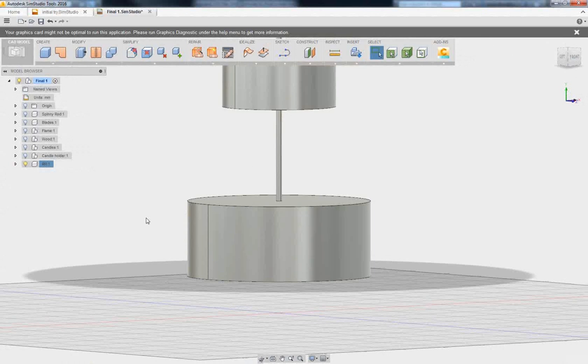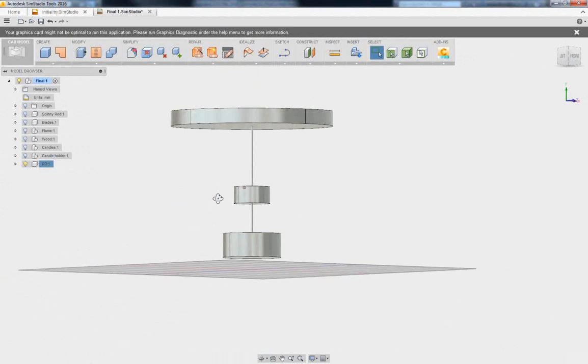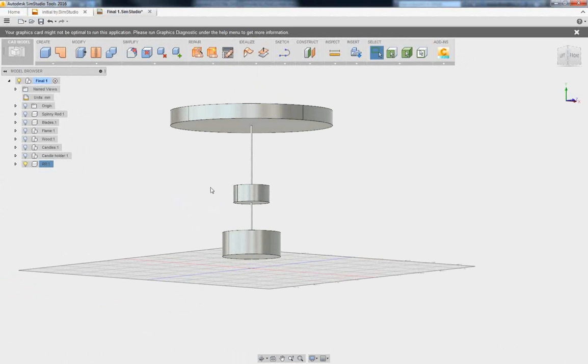As Todd said earlier, he tried to just cover up the blades at first. And there used to be this weird trick where if the rotating region was touching a solid, it would then also rotate that solid, if meshed solids were touched. So if it kind of broke through the rotating region, what you used to see is the housing for a pump would spin, is how we would spot it. So you're like, this looks absolutely ridiculous, my housing is going all over the place. And I was like, can I use that to my advantage? No.